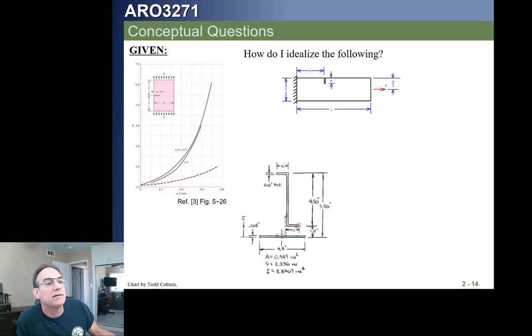How about this guy here if we have this little part? Now there's two ways we can do this. We can do it on a flange-wise basis. If I say calculate this on a flange-wise basis, we can calculate what the stress is in this flange and just pretend this flange is the only thing there is. In that case, the B in the figure will just be this dimension, 1.1. Or if this part is in bending, then that's actually a really good approximation.